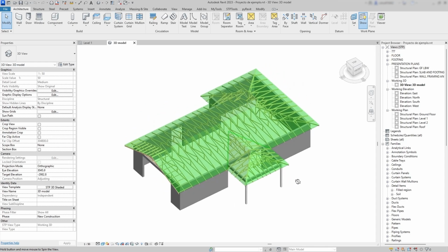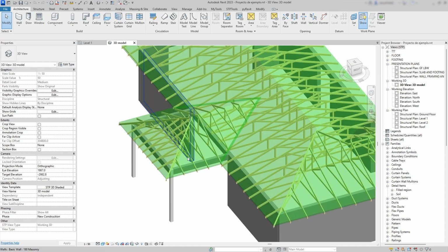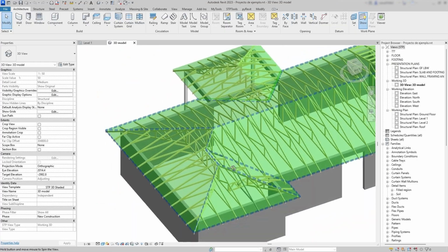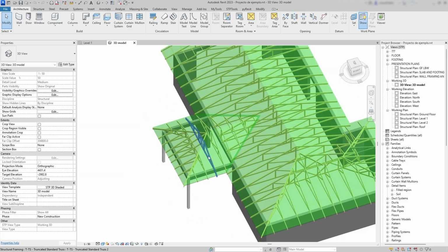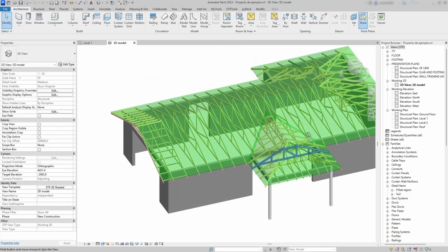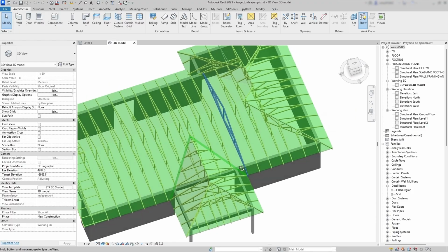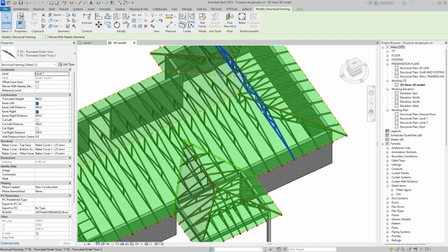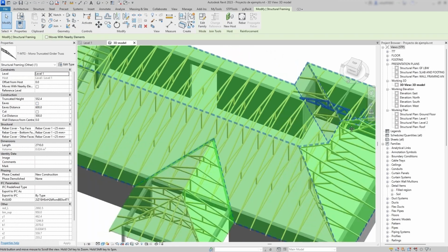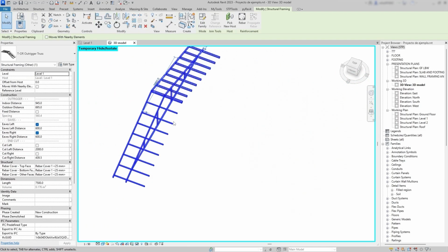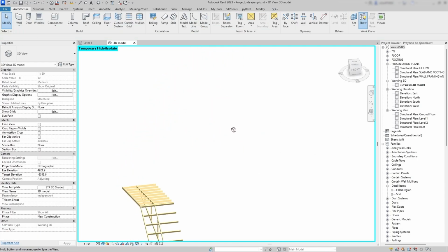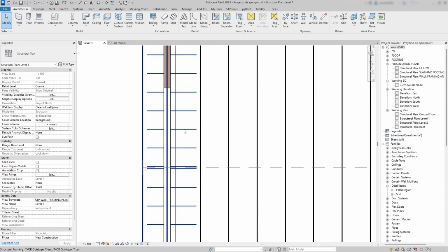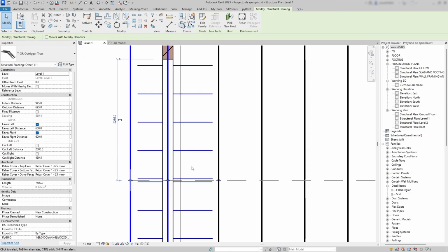That's exactly why I've also created other truss types to handle most of the real-world scenarios you'll run into on actual projects. In the next videos, I'll walk you step by step through how to build a more complex roof, using additional truss types like valley trusses, mono-truncated trusses, roof rafters, hip rafters, and even this really cool gable end truss. With this one, you don't just get the truss itself, you also get all the outriggers built into the same family, so you don't have to worry about modeling every single outrigger one by one.